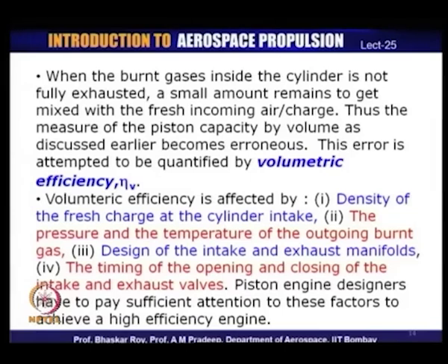So, all the burned gases do not go out of the cylinder, a very small amount remains, and when the intake valve opens and the fresh charge or fresh air comes in, it gets mixed with the residual gases, and what you get finally is a combination of fresh air charge and a certain amount of residual burned gases that has remained after the exhaust stroke.